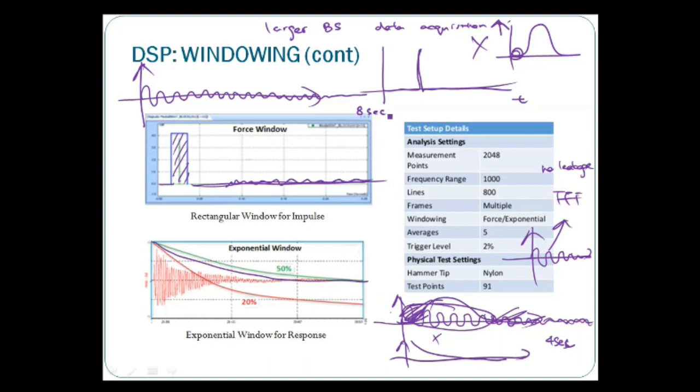So instead of 4 seconds, I use 1024 and 4096, right? Just now, sampling rate and block size. So at 4 seconds, it doesn't end at 0, right? But then if I go up to 8 seconds, if I increase this to 8192, so my acquisition time is 8 seconds.